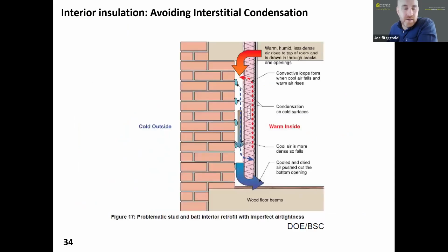You don't want to pull the dry line off the wall where the space between the dry line and the wall is unventilated. Warm air will leak in there, and as it gets into that cold space, it'll get denser and it'll lose its moisture. And of course, we've seen the images of what can happen when that happens. So unless you can ventilate that space to the outside, top and bottom, don't do it.